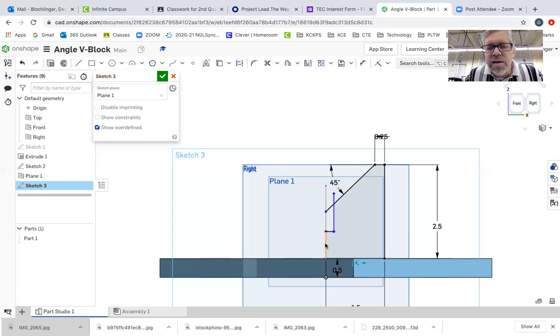And so this line should be okay. I want to do a D for dimension. I was over constraining. So half of 0.25 is what? Half of a quarter is an eighth, and an eighth is 0.125. Okay, and then from there, we just found our intersection.